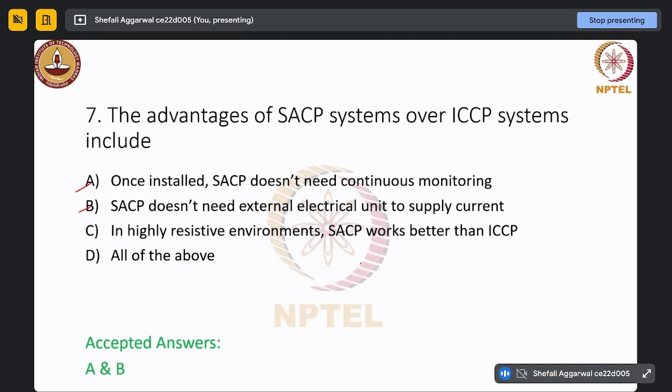Like walls, ma'am, in tunnels or retaining walls, we are doing it, ma'am. Because from 1 meter we have to do it, if the area is small, we are unable to do it. I mean a small exposed area. The depth should not be too much, like if the complete cover depth is there, as far as I know, we don't use shortcreting if the depth is too much.